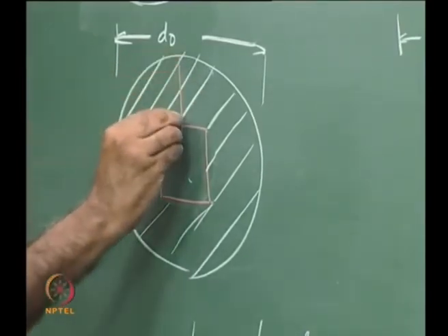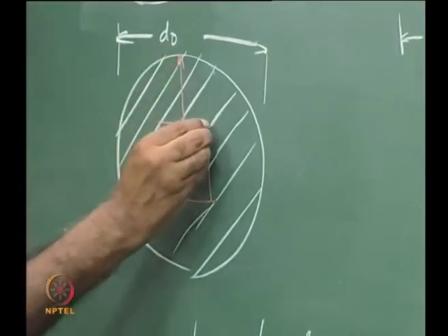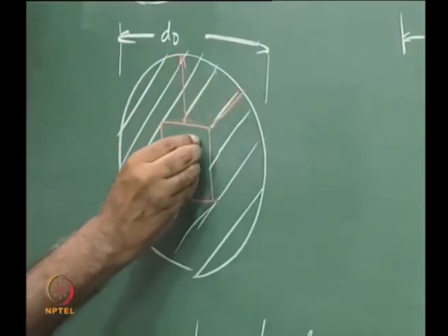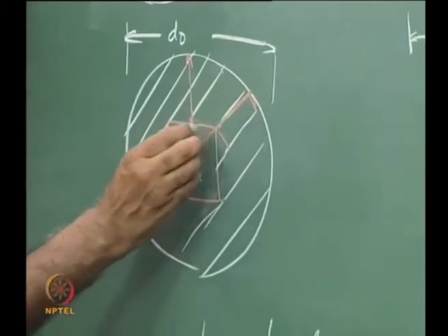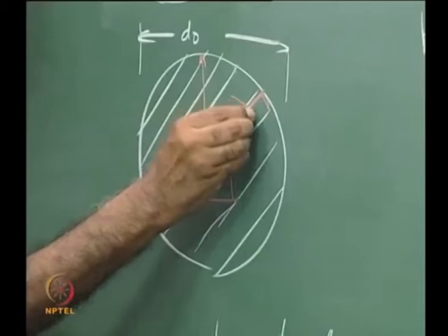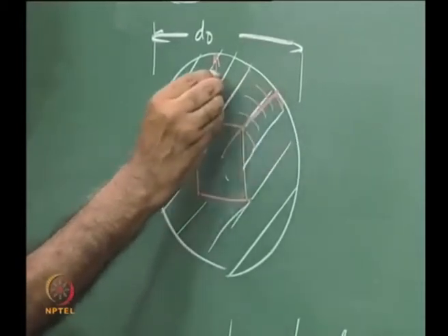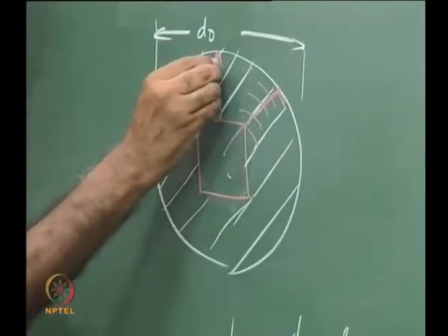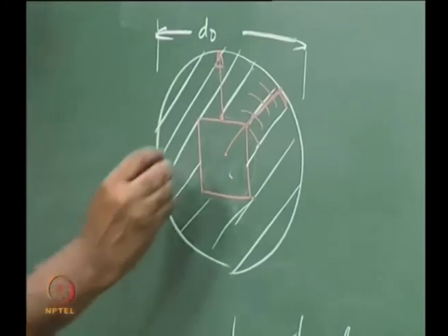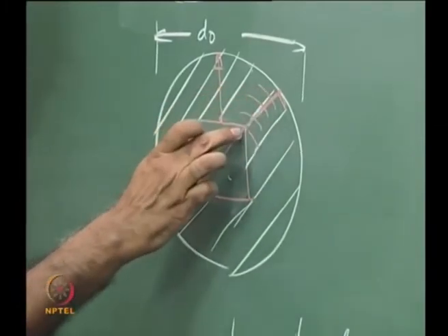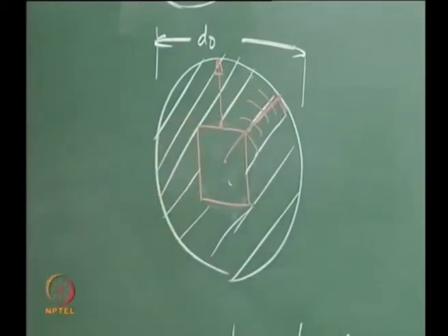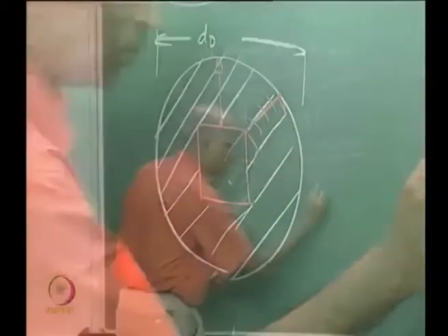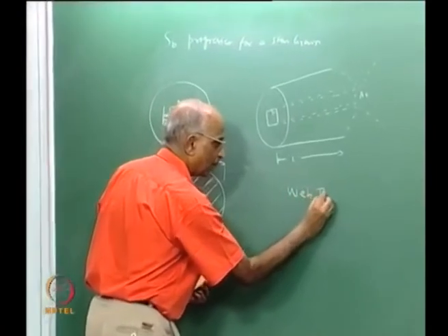This thickness is a little larger. This along the vertex, maybe from here if I plot a line, this is the minimum distance, and as the grain evolves it goes as a circle and first touches here, because here the thickness is larger, at that point it is coming only over here, and therefore this thickness between this point to the casing is the minimum thickness, and this minimum thickness is what is known as a web thickness.